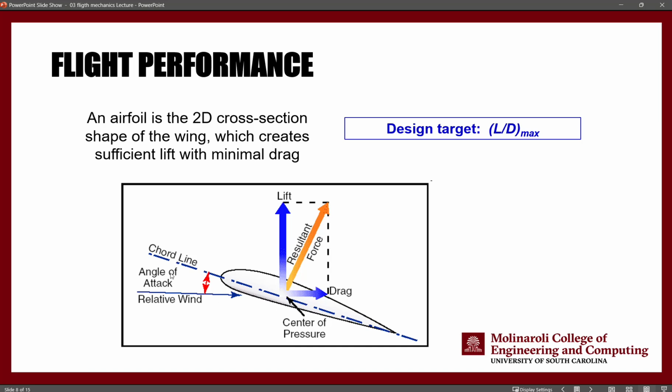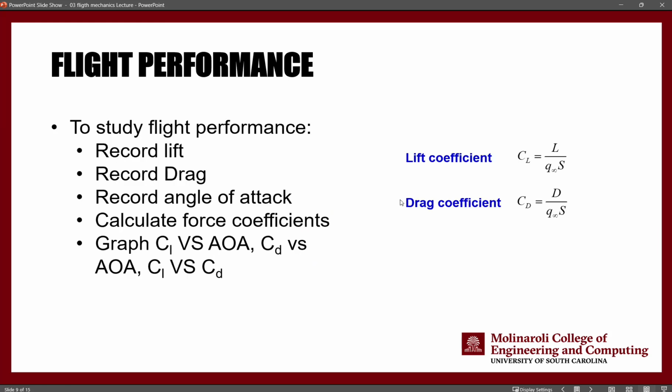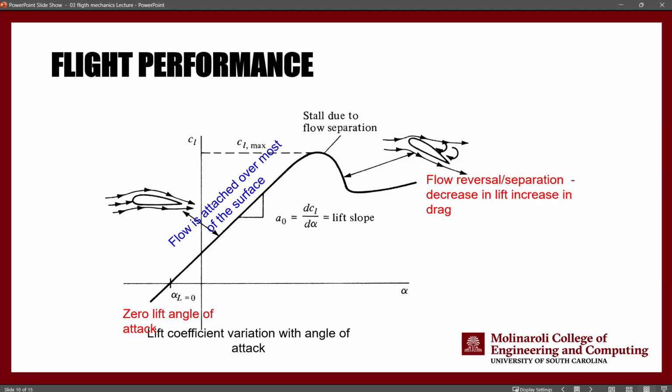So essentially, if this wing rotates to very low angles of attack or negative angles of attack, you are going to see a reversal in the direction of the lift. Is that always a bad thing? No, depending on the conditions. But usually we don't want to see that. Like in general types of flight, you definitely don't want to see your lift working in the same direction as the weight of the aircraft.